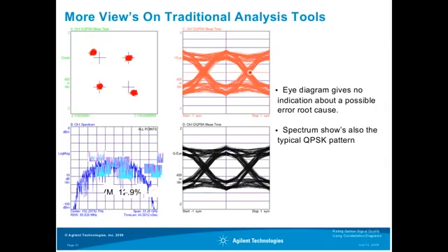In addition, if we look at the error vector magnitude diagram here with a phase distorted constellation diagram caused by the DFB source, we can see a noise that is structured and not even white. And again, we would probably expect that this slight imbalance in the gain would not reflect any structures or impairments in the error vectors.